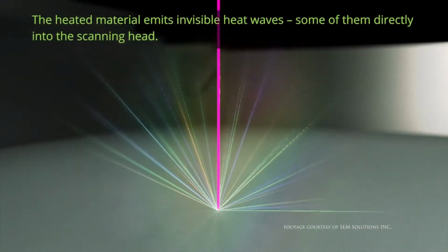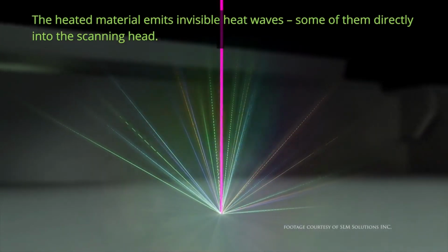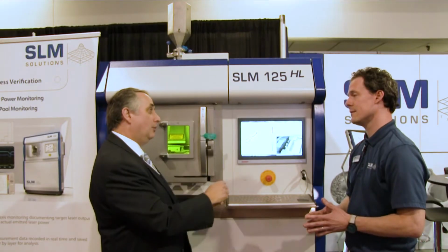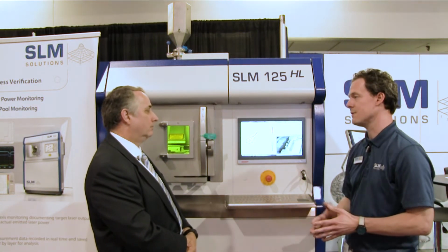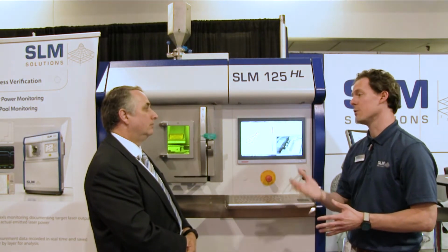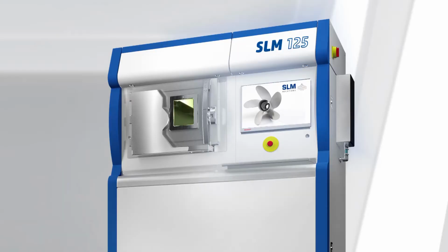Okay, it's interesting. So you're actually sampling the laser light directly, as well as just measuring the reflected energy. Correct. We're taking a beam splitter and we're actually taking a refraction of the laser power as well as the thermal emission from the melt pool in each respective product.